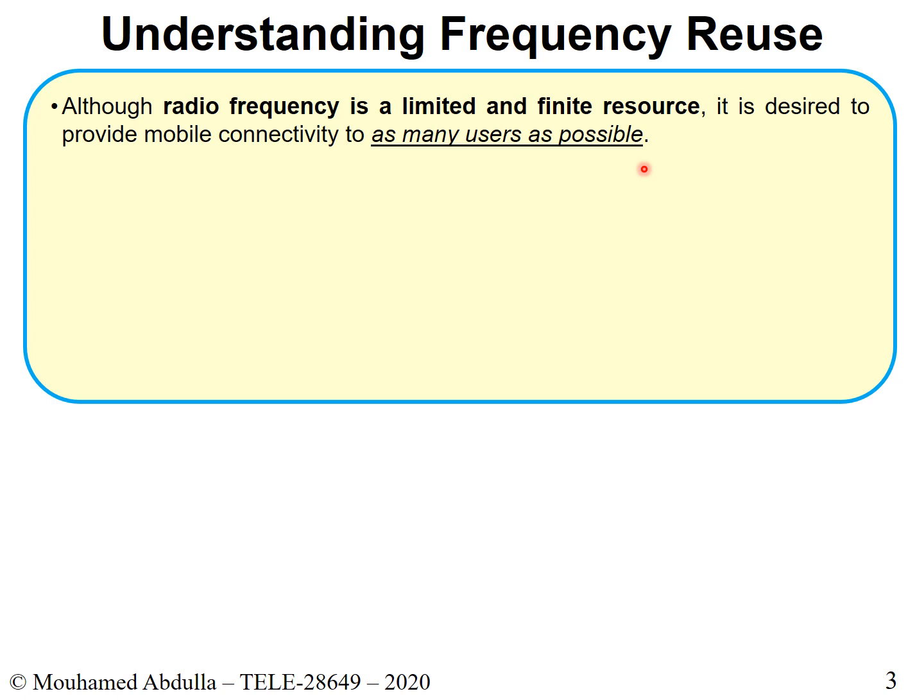I'll just mention very quickly that, for instance, FDMA, frequency division multiple access, was a technology that was used. Essentially, you have a certain frequency range, and you slice that frequency into small chunks of bandwidth. Every bandwidth will be dedicated and assigned to a specific user. That was FDMA. This was used in 1G technology and in 2G technology.